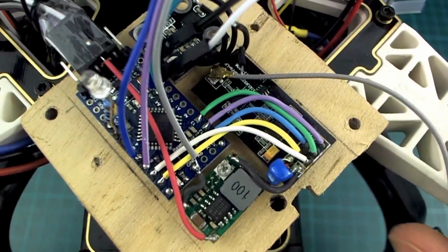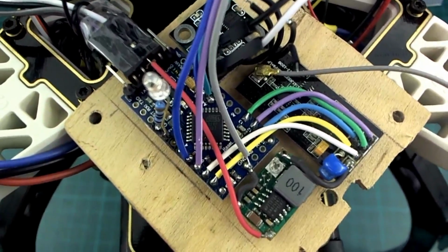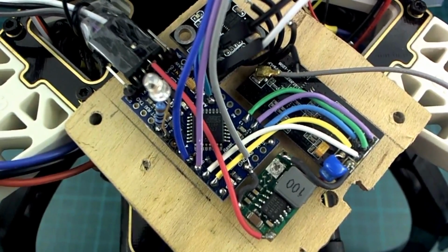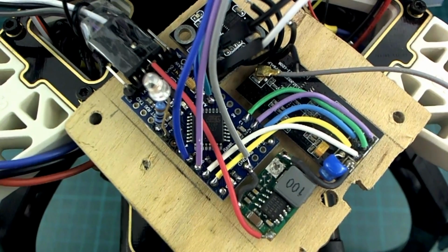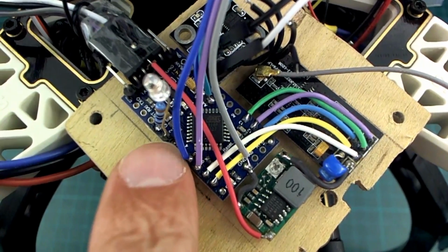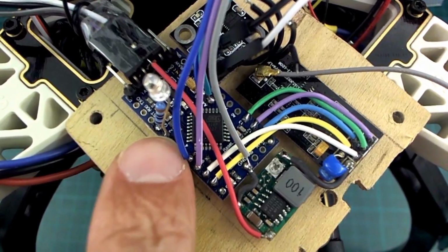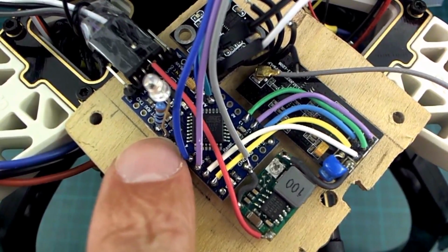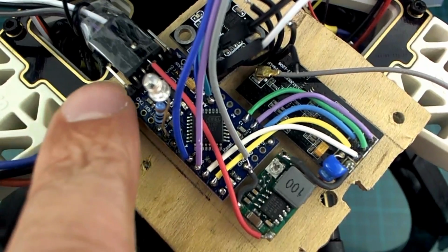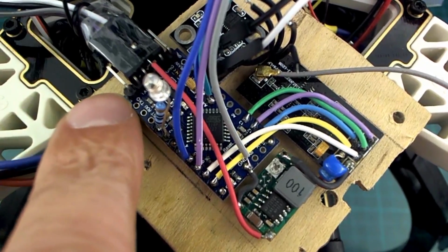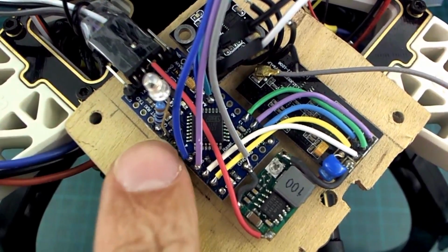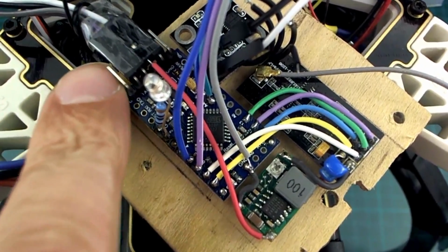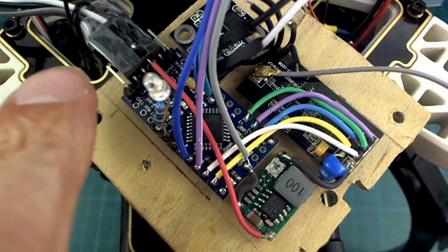So this little piece of plywood, I took this out of the YMFC flight controller that I had for one of my wooden quadcopters at the beginning of this year. It has an Arduino Pro Mini 5 volt. This one really has to be a 5 volt one. I originally started using this with a 3 volt one with a level shifter to talk to the Cleanflight, and I couldn't get it working at all. Everything came right as soon as I started using a 5 volt Arduino, so that it's at the same logic level as the flight controller.